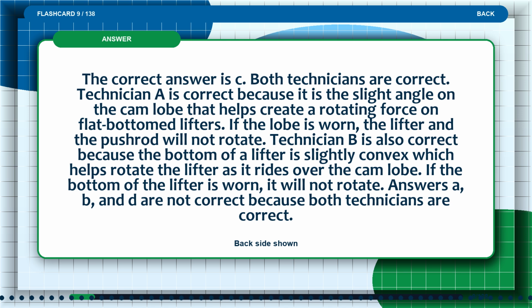Technician B is also correct because the bottom of a lifter is slightly convex, which helps rotate the lifter as it rides over the cam lobe. If the bottom of the lifter is worn, it will not rotate. Answers A, B, and D are not correct because both technicians are correct.